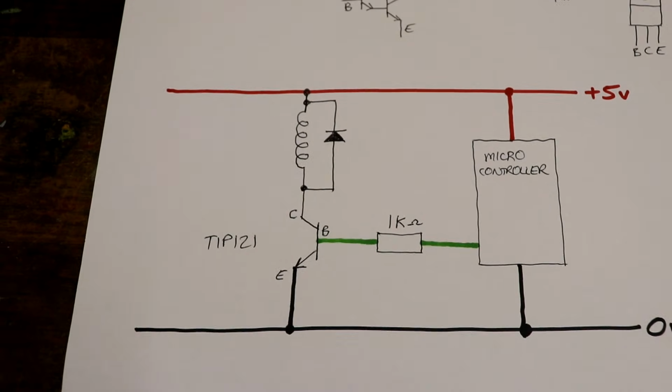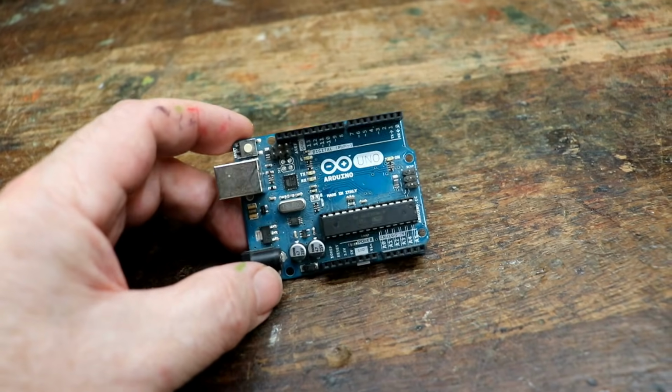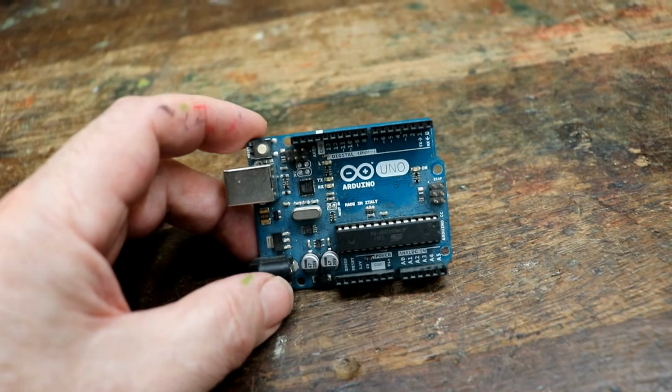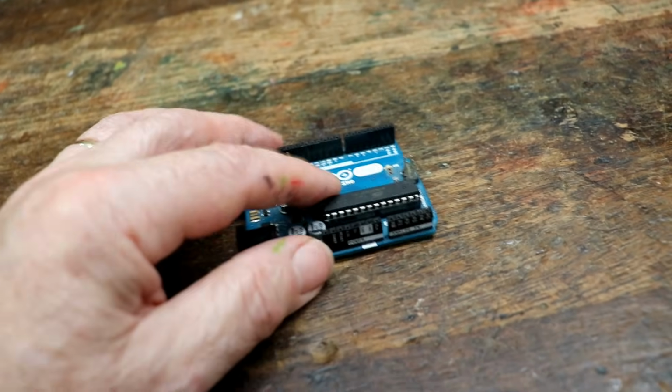Yes. So now it's time to think about microcontrollers, how to actually get these interface devices to control the different types of motor that we're going to use to make our face move. I use Arduinos to control most of my machines, but they're not fast enough to be able to play audio files from an SD card without another huge module attached. Now I appreciate there are so many different types of microcontroller and lots of people have their personal preferences, and that's absolutely fine.